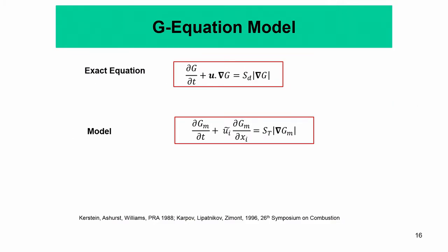Now, how do you use this for turbulence? Okay. Now, as you know, the biggest problem of turbulent combustion, or of modeling turbulent flows, is that your eta, that is the Kolmogorov length scale, divided by the integral length scale, scales as Reynolds number to the power of minus 3 by 4, right. So, as the Reynolds number grows big, the eta by L0 ratio becomes smaller and smaller, right.